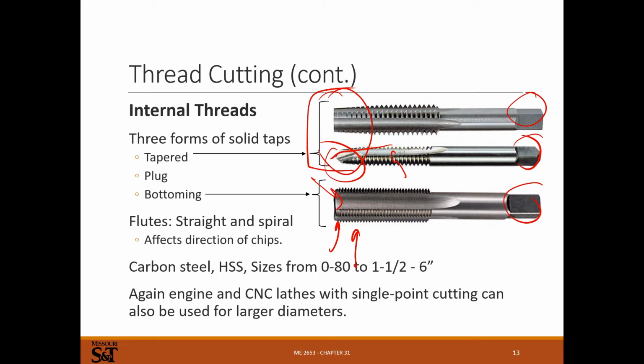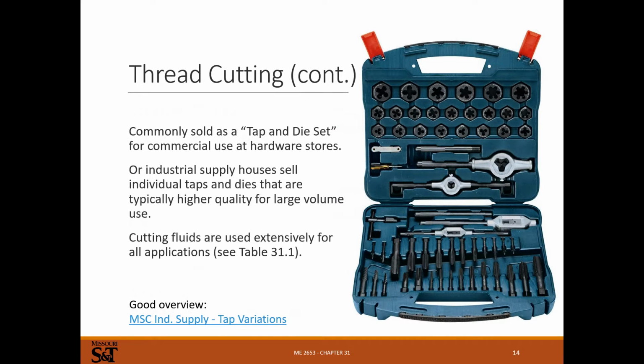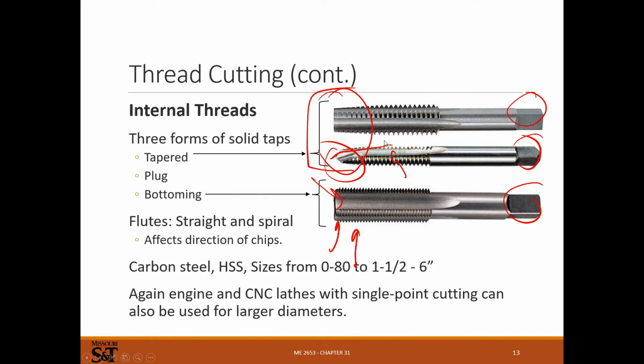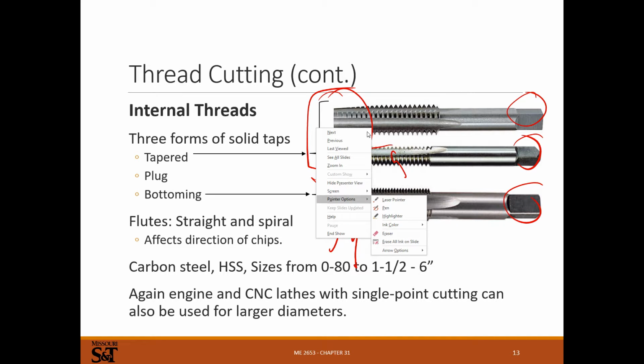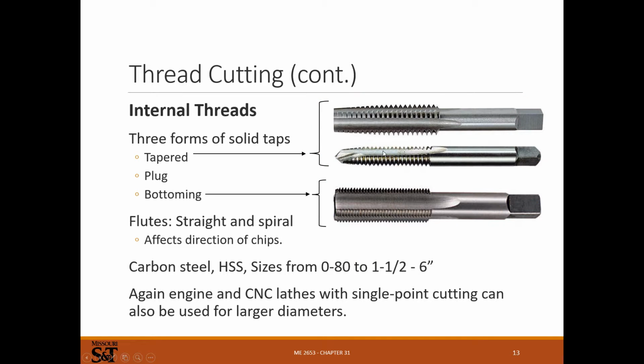Internal threading's a little bit of an art too. I think there's an advanced slide on this. Yeah, there's a couple more comments on it, but what I'll say is that breaking the chip is really important. If you just try to cram one of these things in for smaller taps and harder materials, it's very easy to break a tap.